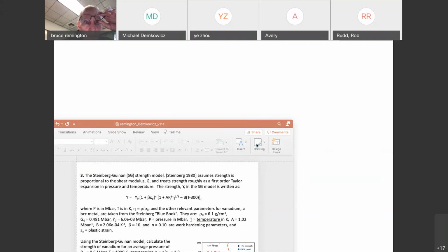It's because as the strain rate increases, you get a higher saturation of the dislocations. The saturation comes about by a kind of steady state of multiplication and annihilation canceling each other. At the higher rates, the annihilation is less efficient. You get higher densities, and so you end up with what is really quite a significant dislocation density, as predicted by these models. Is there anything you'd like to add to that, Bruce?